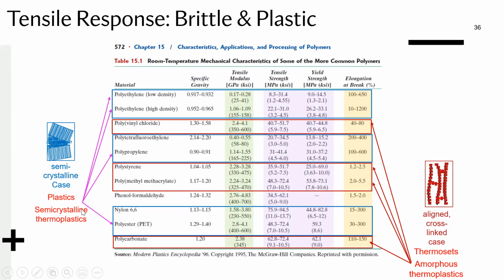They could be closer and closer to crystalline, but as I've mentioned, we don't have 100% crystalline polymer. The amorphous ones, we will see how they differ, but basically if they cross-link to a high degree, similar to a lot of the thermosets, they can have a rather brittle behavior. And this is what you see here.